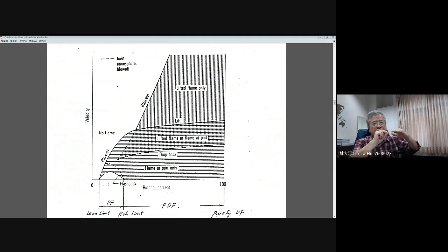Now you continuously reduce the 45 until maybe smaller than 40, because we will find out there is the confluence. The position of your confluence depends on the alpha, the theta. I think you already have this experience from assignment 5 and also the midterm, right? Then if you reduce your injection velocity too much, your flame will flash back.